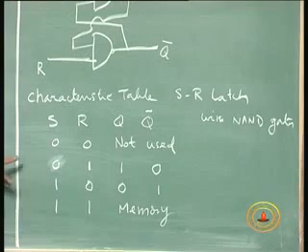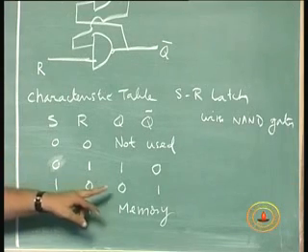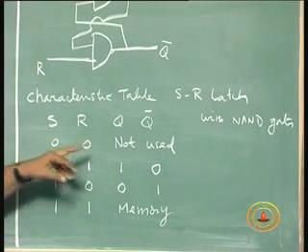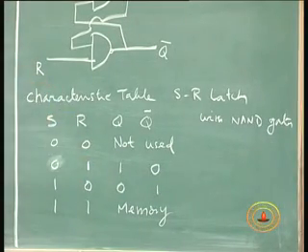Here, when S is equal to 0, the flip-flop is really reset. S is equal to 1, the flip-flop is reset. S is equal to 0, it's set. Because it's opposite, some people call this S bar R bar latch.